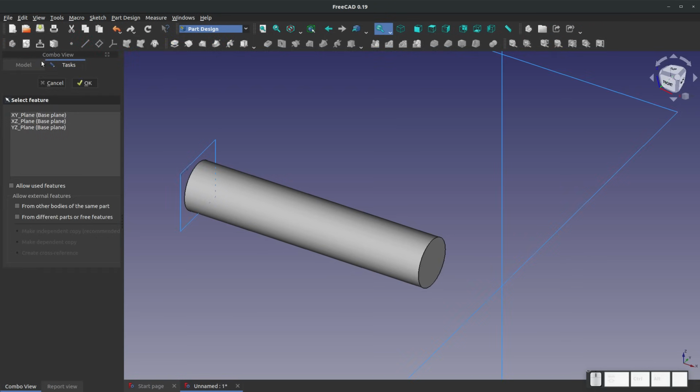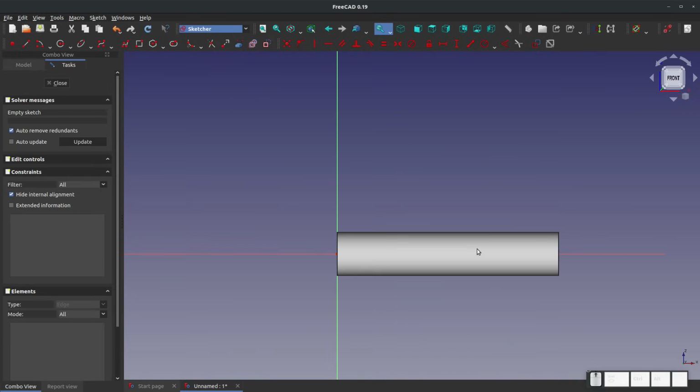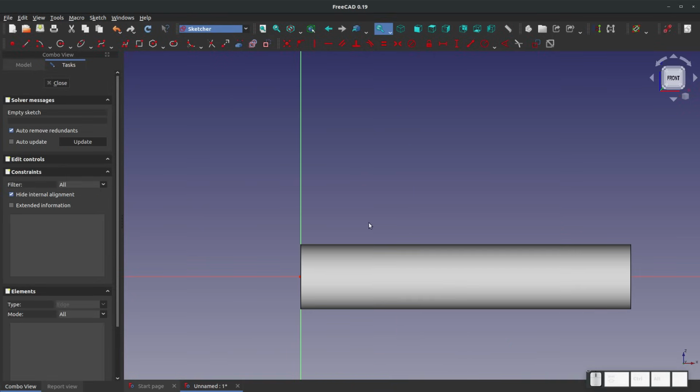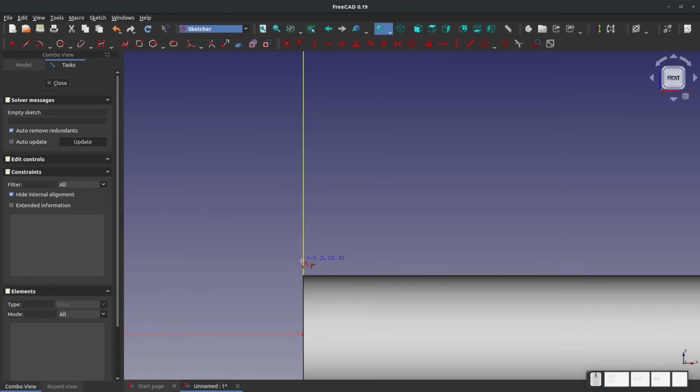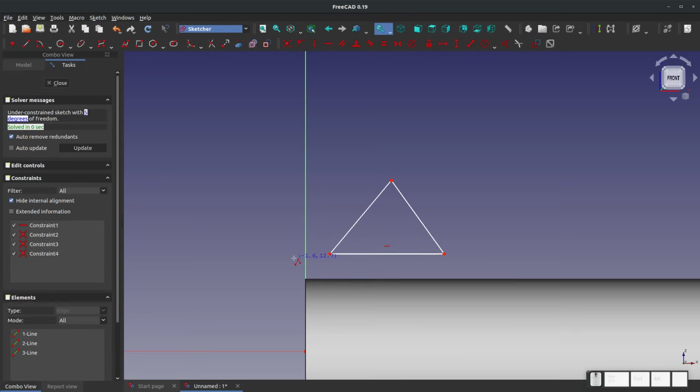Let's create another sketch now. And I want to choose my XZ plane. Alright, so in this sketch, let's try to make a bolt, something that has threads. I'm not going to make this an official bolt, although you can, right? I'm just going to make up some dimensions. Bolt threads look like this. They usually have a 60-degree angle, right? Maybe a little fillet in there.